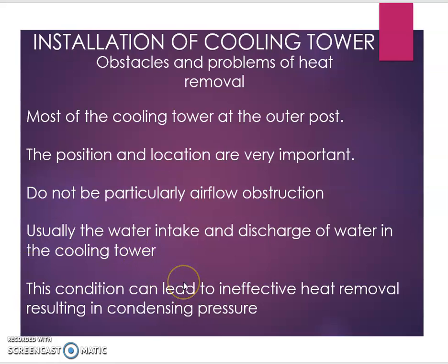We have to make sure there is no obstruction on the airflow of the cooling tower, and the water intake and the discharge of water in the cooling tower must also be properly installed. With no obstruction, our cooling tower will work effectively in removing the heat.